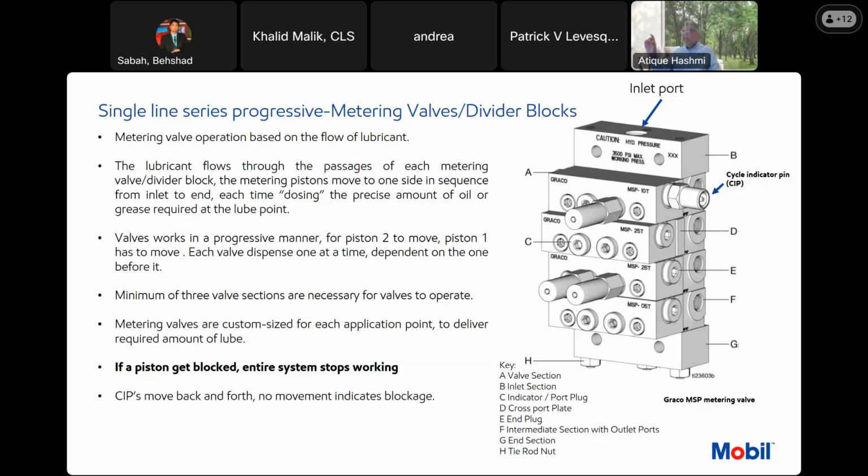So I would assign 40T to the bearing which needs the highest amount of grease per hour. That's how I will assign different Ts and Ss on those divider blocks, just to give an adequate amount of lubricant to each bearing per hour, so the bearings are not starved of greasing. So that's how we select the numbers.